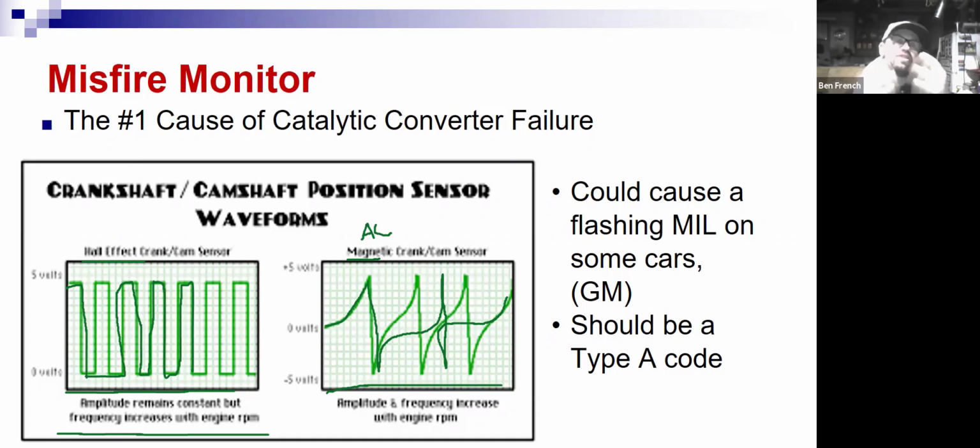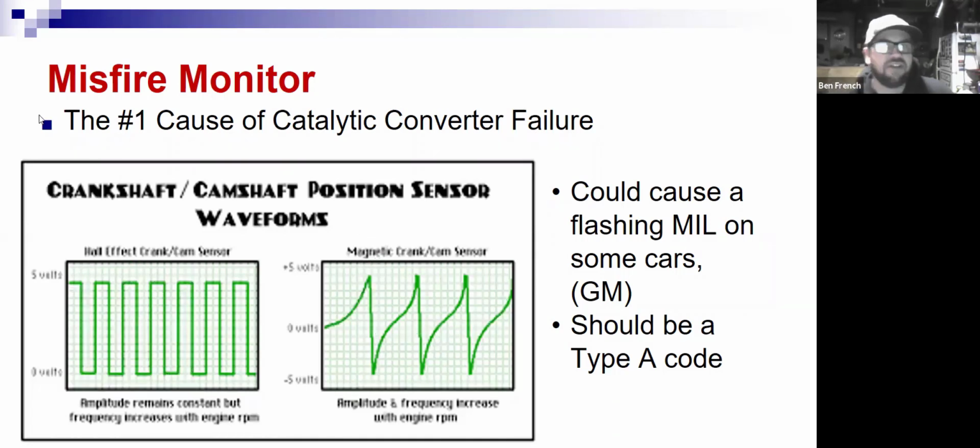So with OBD2 and with the programming that's involved there, stuff that wasn't related before is now related. And that's just gotten that much more so as cars have gotten more and more modern and have multiple computer systems that are all networked together. We see weird things like that all the time now. So now you know how Misfire Monitor works, and sometimes it's fantastic, and sometimes it's a real pain.